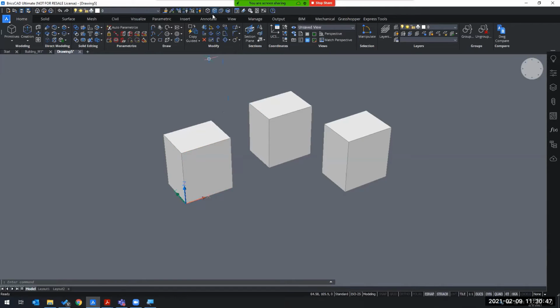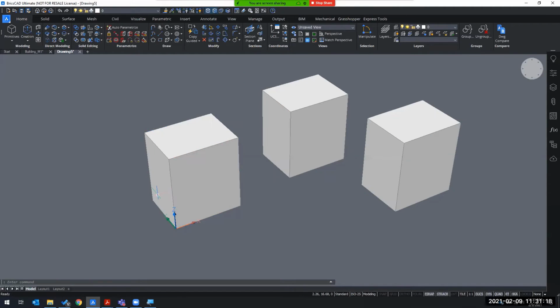Now I'm going to change to edges, and turn off the faces. So now either it highlights the edge, or if I hover through a face, it's just going to take the whole solid. If I come close to the edge, it highlights in orange. If I come anywhere in the solids, then it does the face. I can do combinations of them. For example, now I'm giving priority to my faces, then the edge, and last will be a solid. So now whenever I hover through those entities, it's going to highlight them easily. As you can see, this is my edge. Here is then my face.